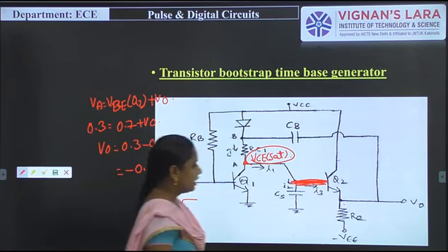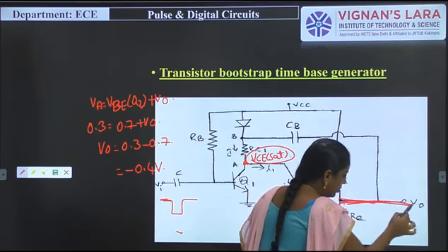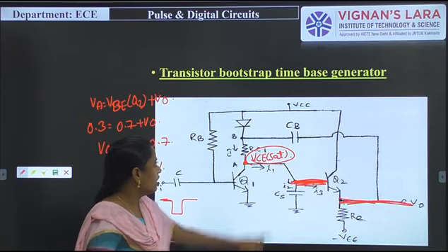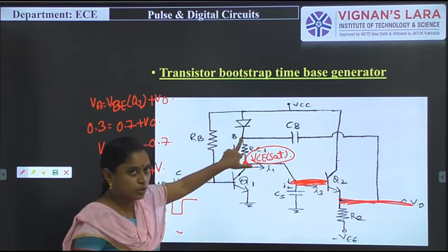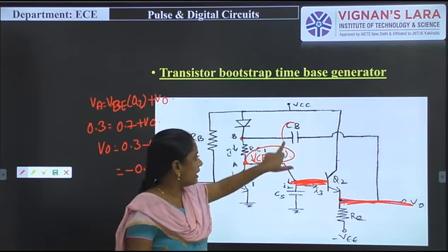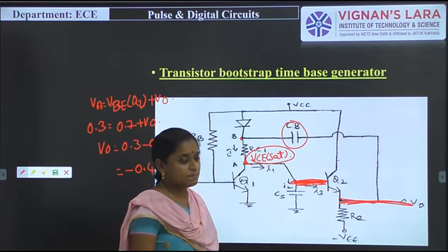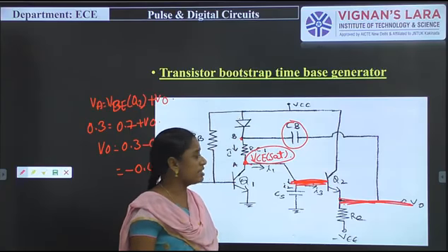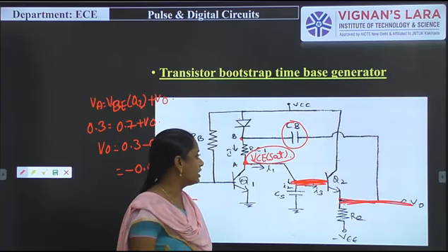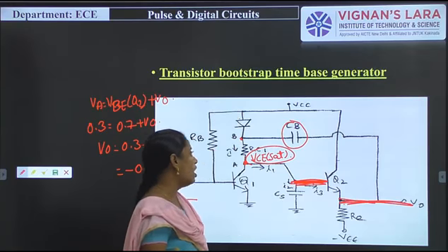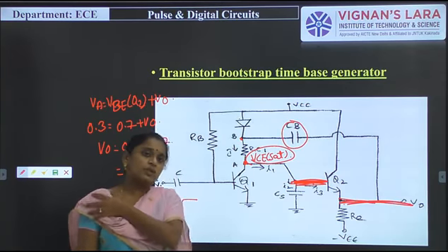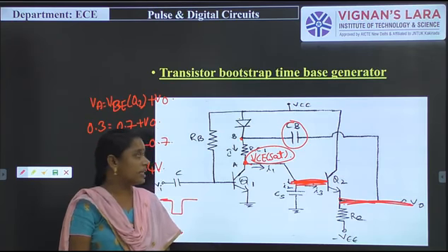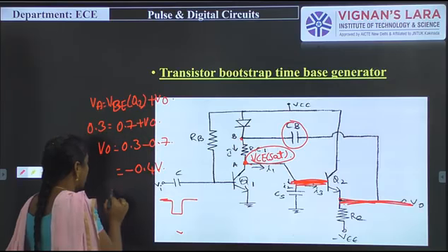So this is the V0 condition; we have to take the output at V0. This voltage is applied to the diode through a capacitor CB. At this particular time, this can be indicated with VCC and this can be indicated as a negative signal. The negative signal is applied to the cathode of the diode and the positive signal is applied to the anode of the diode. So at that particular time, diode D becomes on condition.